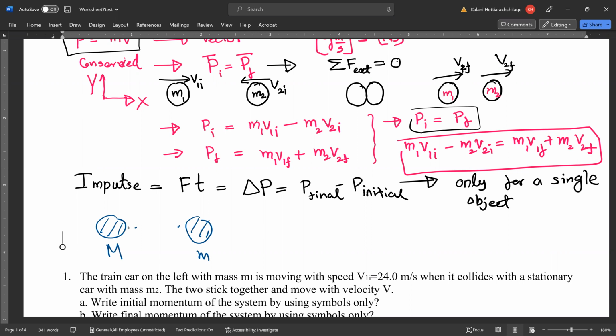Now, how to calculate the center of mass: as a simple example, if you use your x direction here and y direction here, you say, okay, I don't know where the center of mass is. We're going to say this is x center of mass. That distance is from your origin to your center of mass.